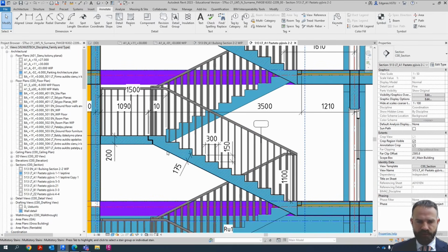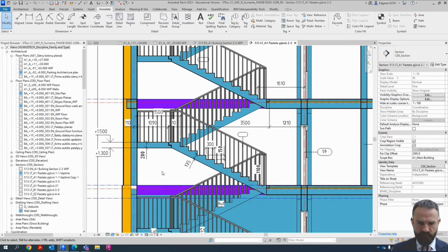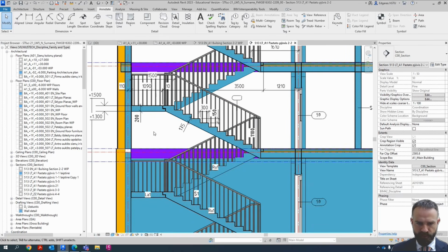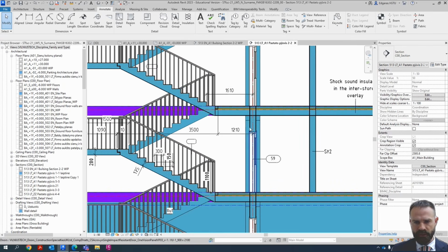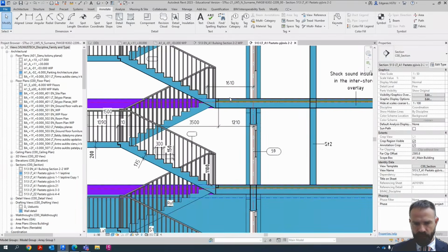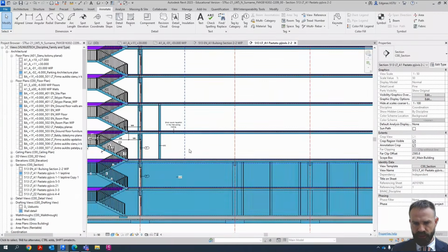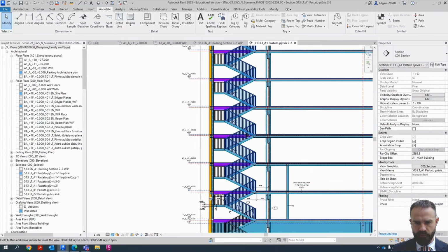Detailed dimensions of the stairs and stair runs are created in separate drawings for fabrication. So we have separate drawings for this purpose. In the main section views, we show dimensions, which help to put the object in the correct position, and we connect everything to the grid line. If we make a section view, we can easily see all the problems.